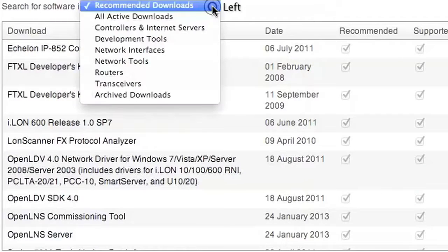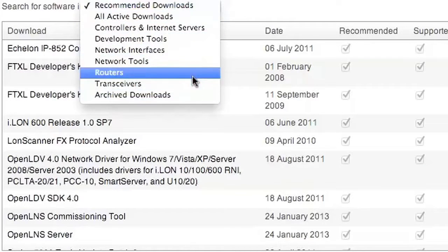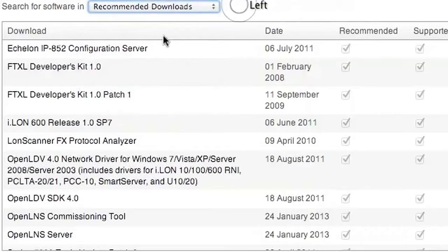With the IzoT Device Stack, you can create devices that discover each other and form communities of devices that share data within the community. With the IzoT Server Stack, you can create a device that acts as a server for the community, collecting all the data from all the devices and making that data available to web pages and other applications. Both stacks are available as free software downloads that include C, C++, and Python source code that you can port to a variety of platforms.